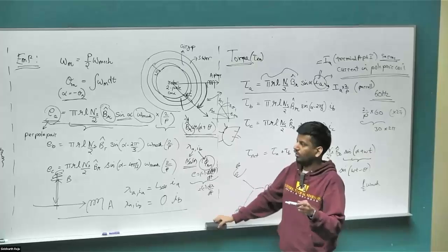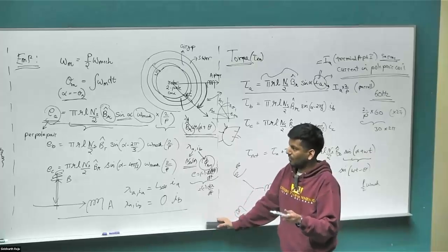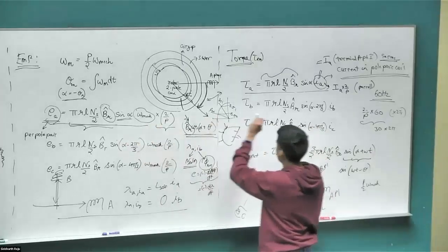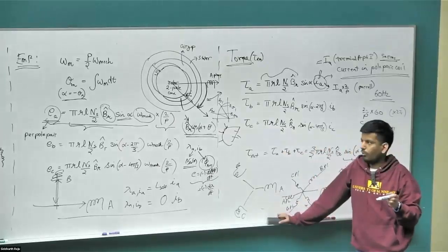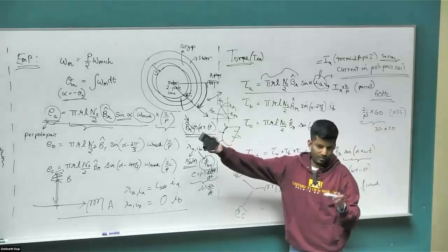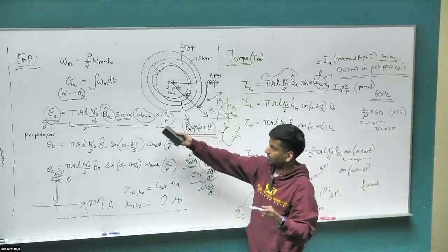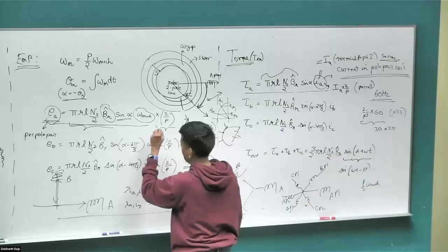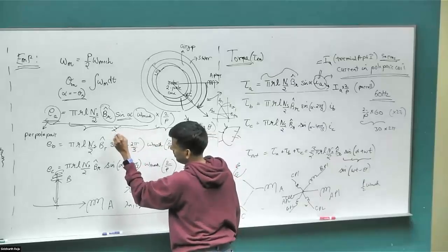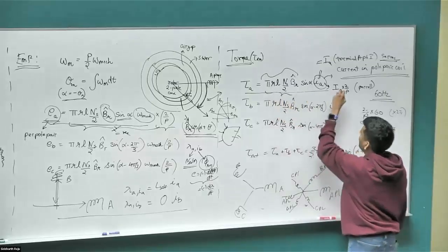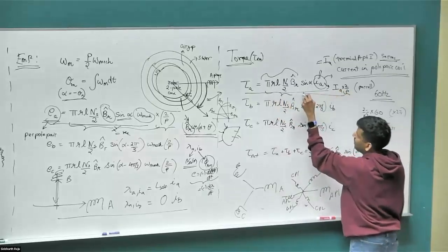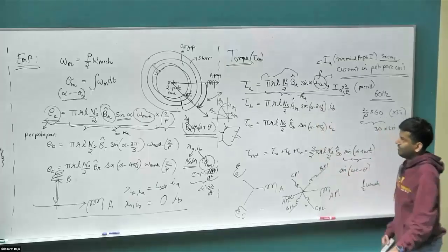Alright, so if you do the model correctly and your KE value comes out different from KT, then you have done something wrong in your pole count assumption. Irrespective of what you choose, the pole counts would come up in such a way that this term times this term, let's call it KE, and this term times whatever factor we have here, KT, should be the same irrespective of how you do the motor.